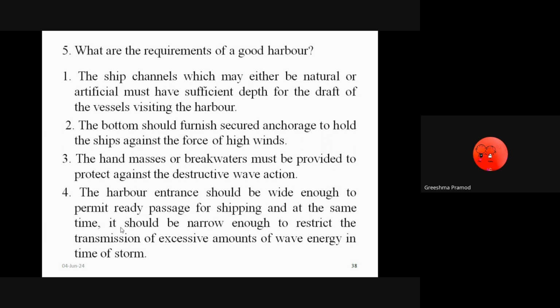What are the factors to be considered when you select a site for a harbor? Marine conditions should be favorable without any disturbances from the sea. Then the foundation or seabed must be properly checked, whether it is able to bear the breakwaters against the wave forces. The site should be economical and the construction materials must be easily available. Water should be fresh without any pollution. The harbor should be easily reachable. Then surrounding areas should be developed with factories and industries, so that exports and imports of goods will take place. Right.